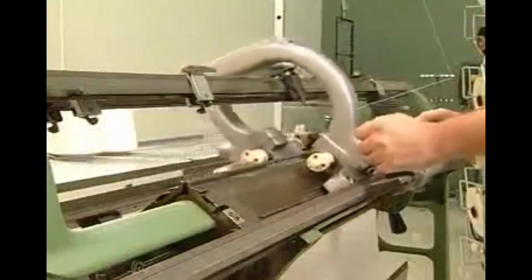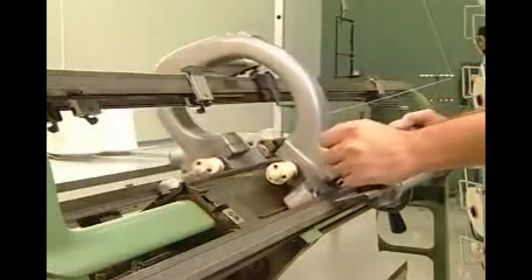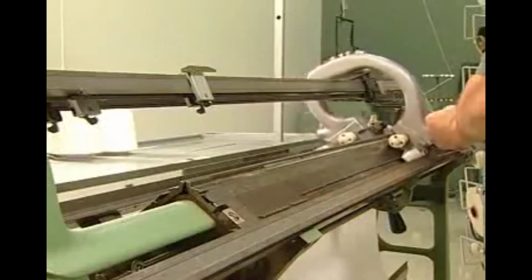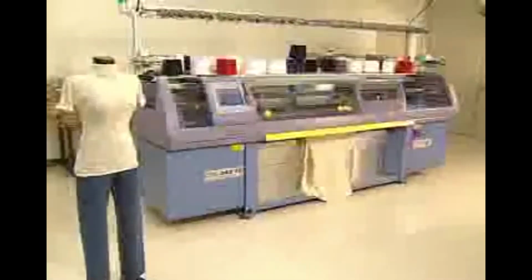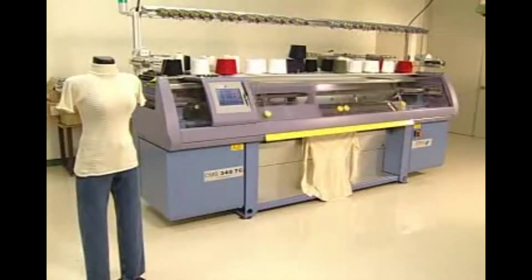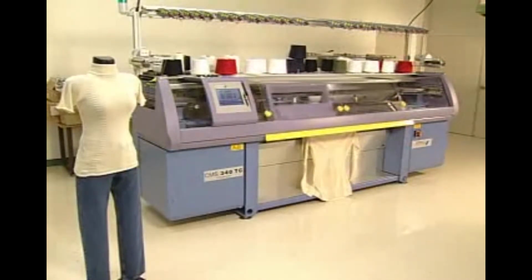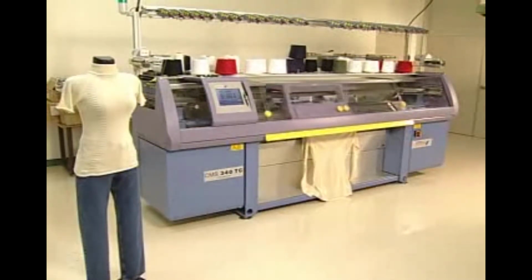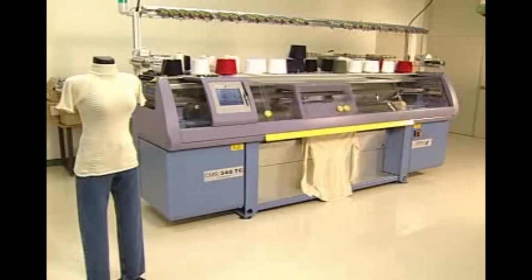Another type of weft knitting machine, designed to make single and double knit fabrics, is a flatbed machine. These machines may have the 2 needle beds in the same plane, but usually they are set up in a V configuration and then referred to as V-bed machines. These knitting machines are used to produce tubular fabrics or flat panels that can be put together to form a garment. Because the width within a panel can be made to vary, this system minimizes waste and sewing. Also, the technology has matured so that a complete garment can be made on this machine.